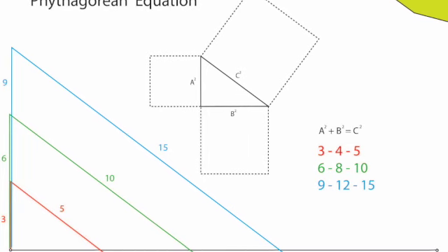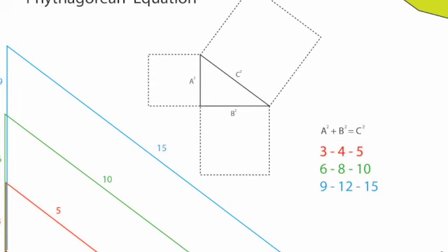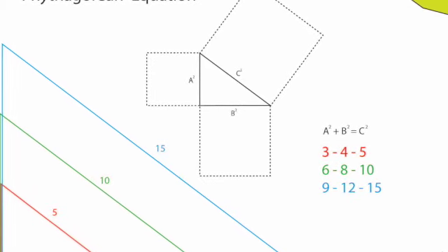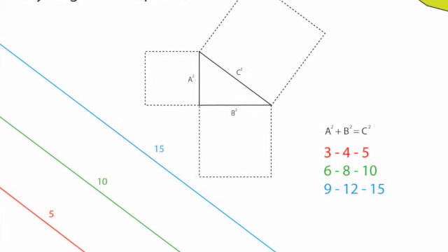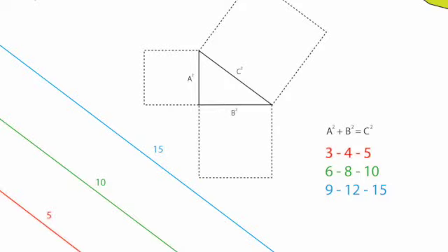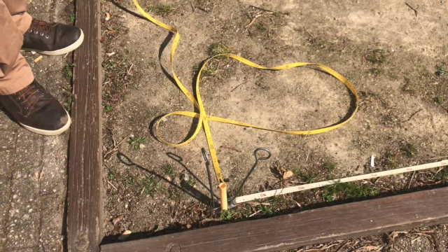Because the measuring tapes are at a 3-meter interval, we can either use the 3, 4, 5 sequence, the 6, 8, 10 one, or the 9, 12, 15 one. But the bigger the number, the more difficult it is to make an accurate triangle. In this example, we will use the 3, 4, 5 sequence. For this, you need an extra measuring tape and surveying arrows.